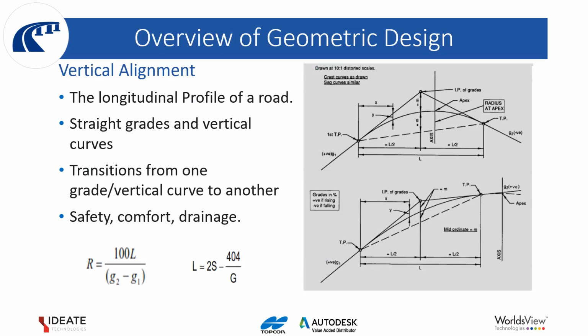The main factor to consider is still the radius of the vertical curve, which is largely determined by the grades, that's the grade in or grade out. Plus, you still need to consider the lengths or distances for passing and stopping sight. So that if someone is approaching a particular mountainous area, going even to smaller details, like the headlight, when he's approaching a particular sag, the headlight should still be able to project far enough to allow him to see an oncoming vehicle, if he is driving at night.